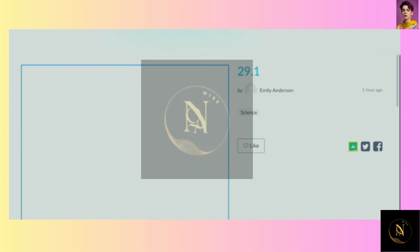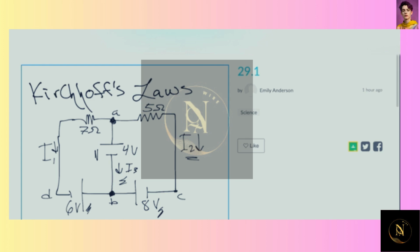And for that, I need Kirchhoff's loop law, which tells us that around a closed loop, so say going from A, B, D back to A, from A, C, B back to A, or A, B, C, A, or A, D, B, A, that total change in potential is going to be equal to 0. All right, so I'm going to look at this loop here, going from A to D to B back to A. I want my total potential change to be 0. So delta V equals 0.